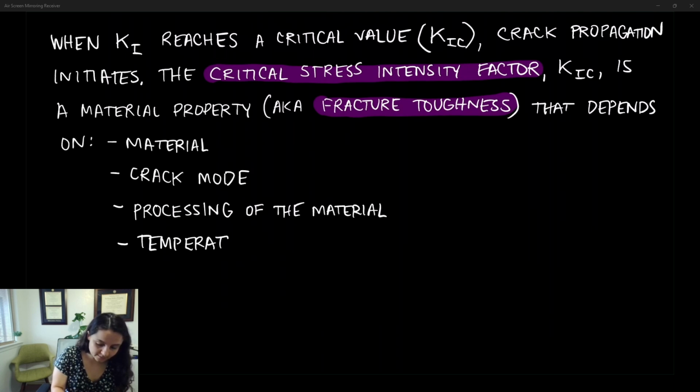We know that materials behave in more of a brittle manner at lower temperatures. So if you have a very low temperature application, then fracture mechanics should become more of a concern at lower temperatures. Loading rate also matters.